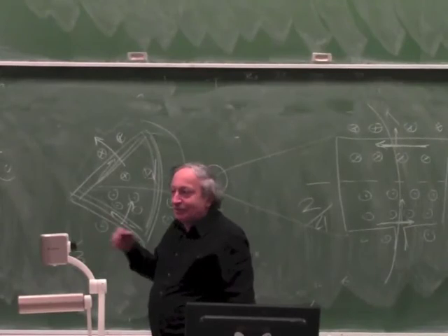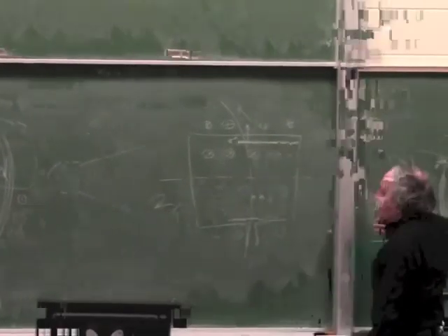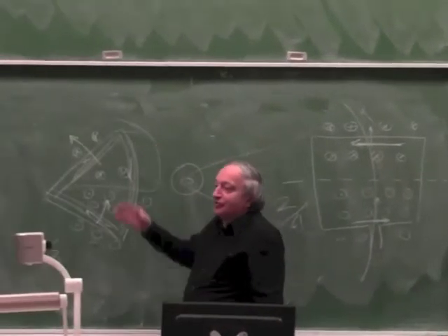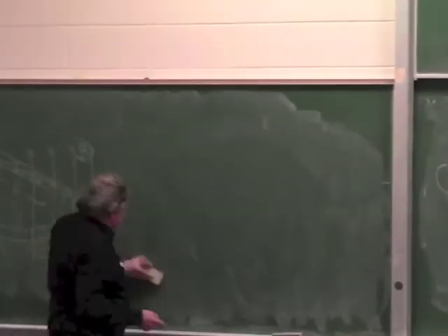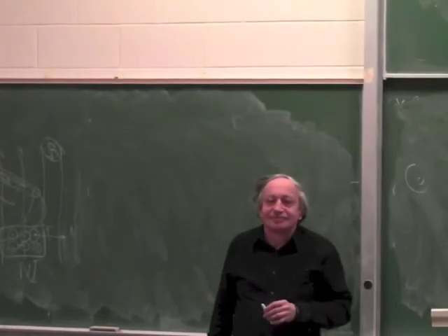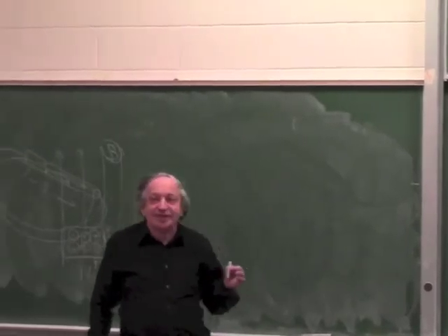Okay? But what if we wanted 4 out of 4? What if we wanted to go back to a linear actuator, and we actually wanted every piece of copper to produce force? How do we do that? So something you all own, of course. Very simple. What we do is we do what a loudspeaker does.